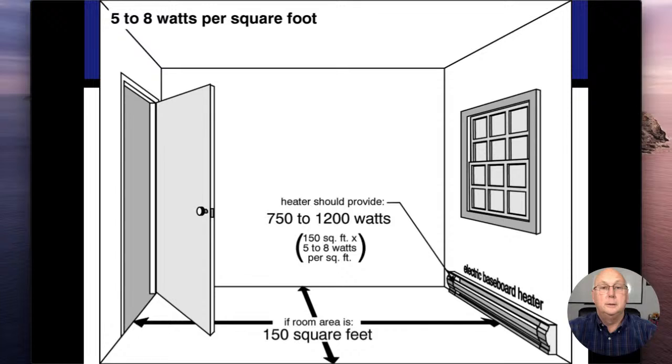All right. A couple more slides, and we're going to wrap this up. We do have to have a heat source in every room. This is something that I see overlooked when we do our field training on some of these homes. We've had houses that didn't have a heat source at all in it, and it just wasn't recognized, because if we don't see it broken and it's just not there, it doesn't really look like a problem.